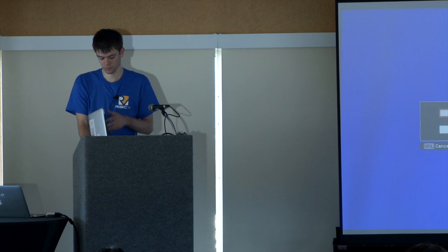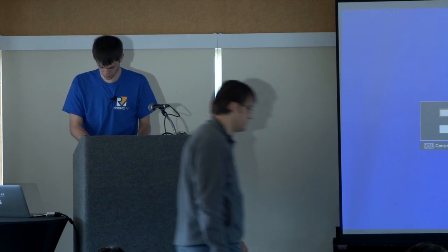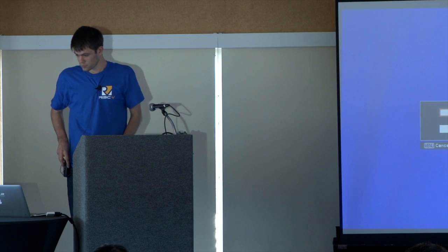Yeah, so I think I can help answer this one. The C++ test harness is actually, once you generate this Chisel module, it will have the IOs. So you can read it every cycle, and your test harness is calling the tick function every cycle. Once you call that, you have all the IOs sitting there, and then you are just writing general C++ code to read them out. So sockets and everything else, you can all write that in your test harness.